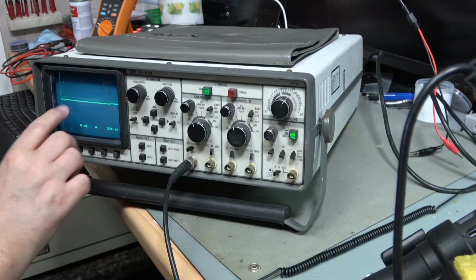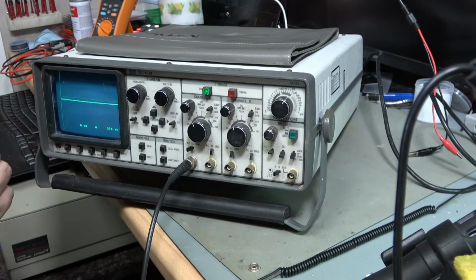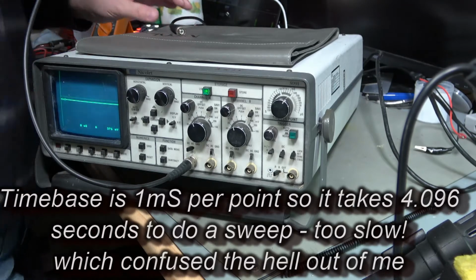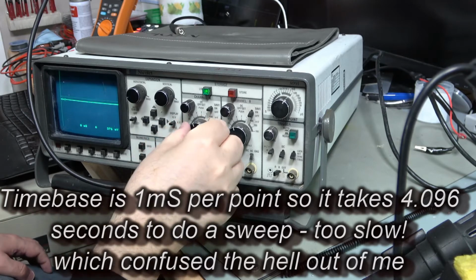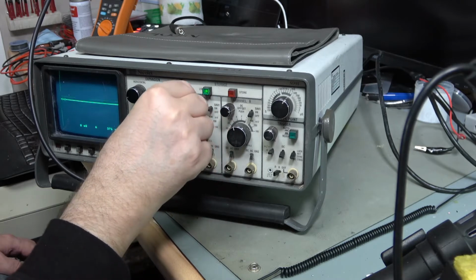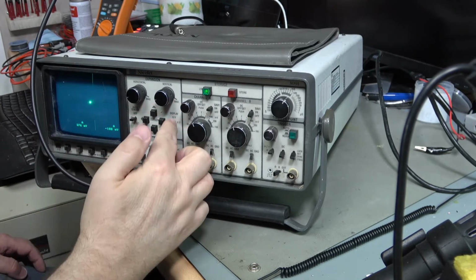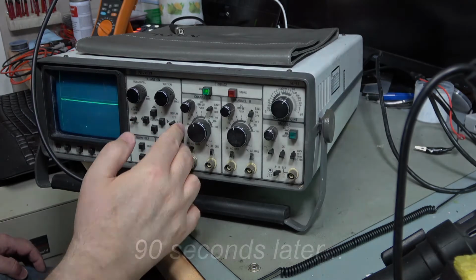I'm not sure if you can see on the screen, but there is a little bit of noise where this was plugged in, and the trace running across the screen. Let's get this plugged in, and this is 4 volt peak to peak 1 kilohertz, so that should be alright, shouldn't it? Let me just have a look. I am looking at channel A in DC. So this definitely works. That's an XY display. This is a Y time display.